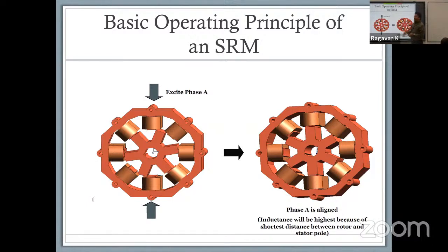The one thing about an 8/6 switch reluctance machine that is unique, and I won't talk about that very much, but you can look up a paper written on the topic of an auto calibration model for a switch reluctance machine. We wrote that several years back, but we have taken that forward for a 6/10 machine since then. The idea here is in an 8/6 machine, there are some very predefined steps. First and foremost, you apply current here. The closest pole that you have aligns itself, and this goes from unaligned to aligned position.